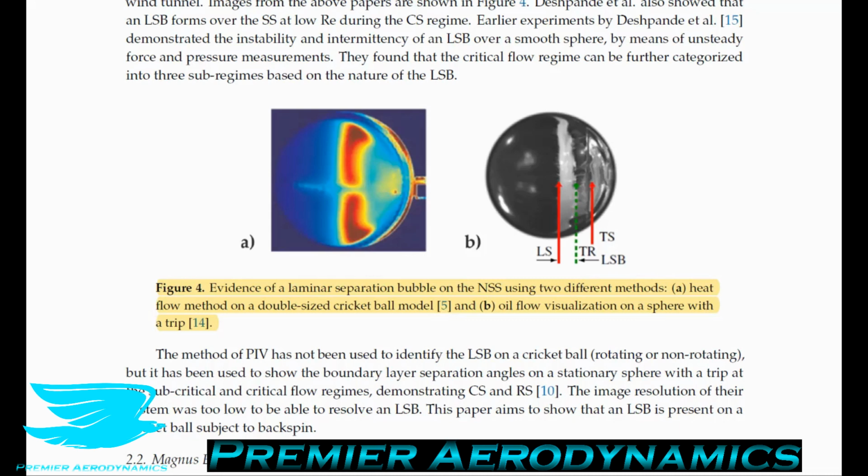So as I mentioned in podcast 24, which talks about laminar separation bubbles as well, the boundary layer can transition through a bunch of different ways, going from not at all to bypass transition, and it really depends on how great the perturbation in the boundary layer is. Laminar separation bubble sort of is on the more gentle side of the spectrum, as opposed to the bypass, which is like a massive shock to the boundary layer, and it creates widespread turbulence very quickly.